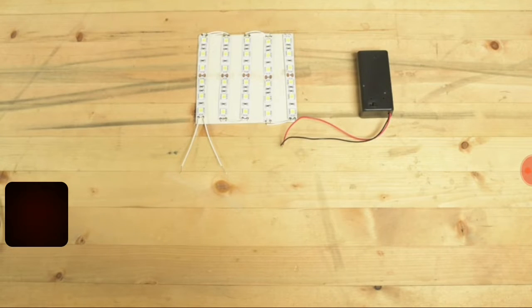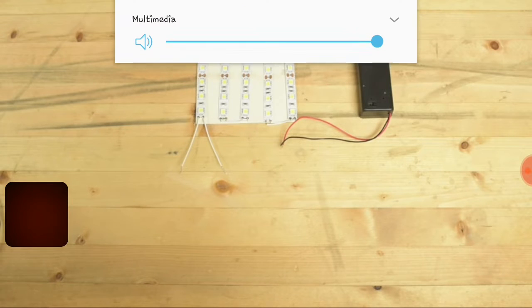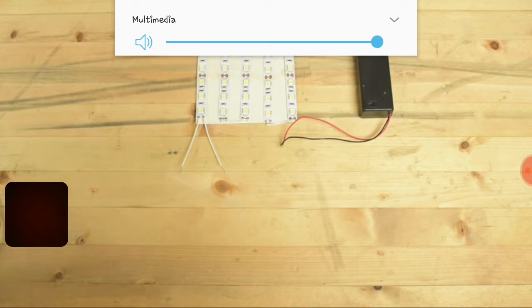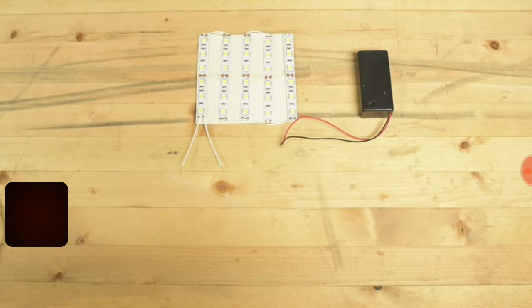So today I'd like to talk about two different ways to control LED brightness. So LED dimming, basically. First, I'll show you the most straightforward way. The most straightforward way to dim an LED is to reduce the current going to the LED, or possibly the voltage, or both.